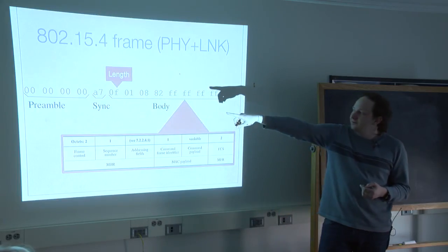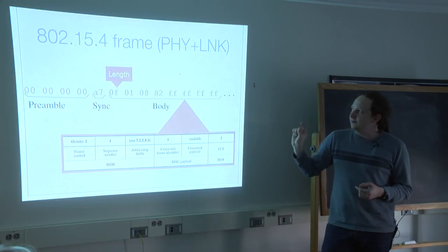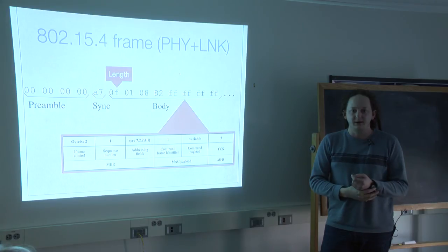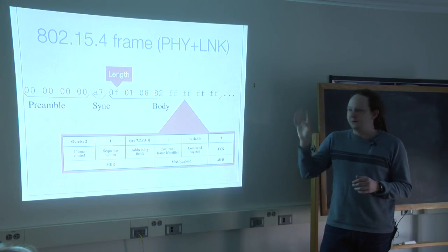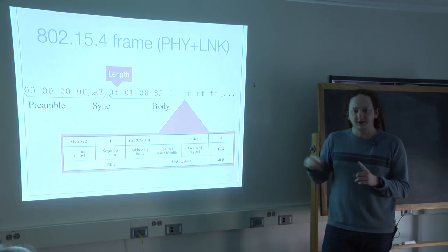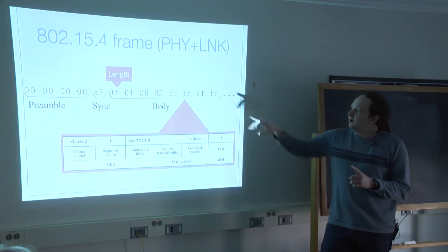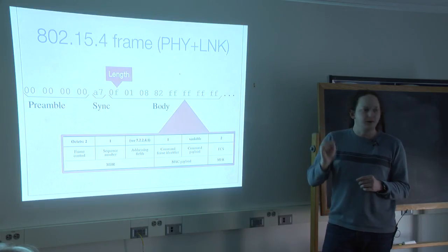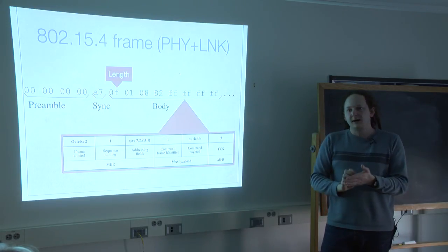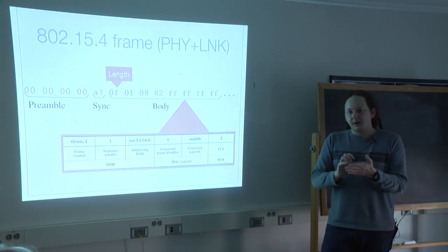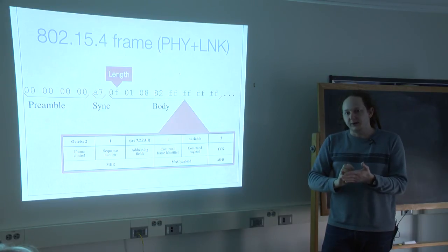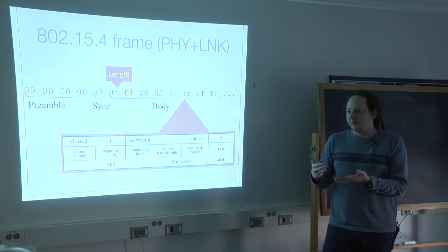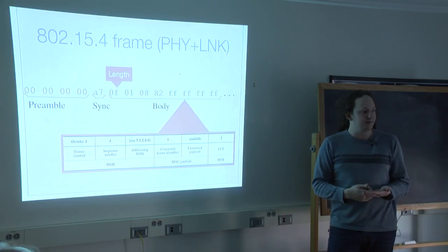These are the zeros. The zeros symbol in 802.15.4, it still wiggles around a bit. It's actually 32 ones and zeros at the lower layer. So these preambles, these 0 bytes, are used so that the receiver knows what bit timing the transmitter is using. Otherwise, the clock drift would be so severe that by the end of the packet, the receiver would not know where a bit begins and ends. And in drifting off, it would begin to make mistakes in identifying those bits.